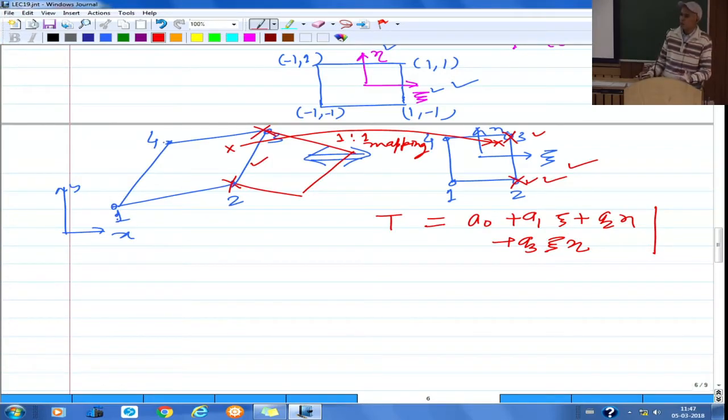So you will find that 1 dimensional problems you can either do using physical coordinates, the way we derived, assuming polynomials in x and then developing the element level governing equations, or even you can do that in the natural coordinate space. It is actually not a mandatory requirement, but you see here, if I want to have arbitrarily shaped elements in physical coordinate space, then I have to have the formulation or the interpolation of the field variables in the natural coordinate space.